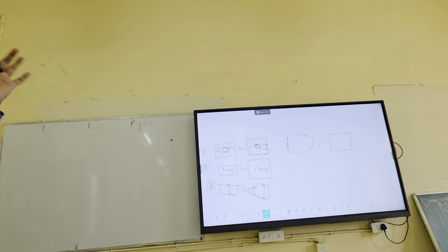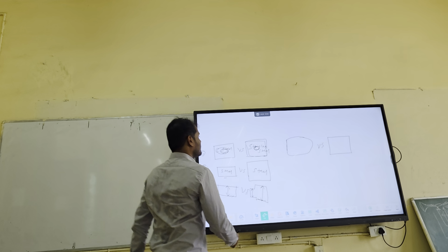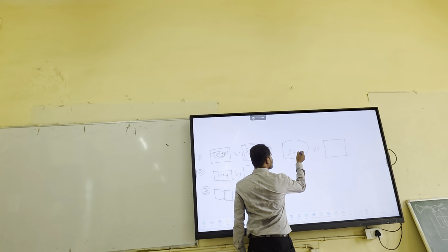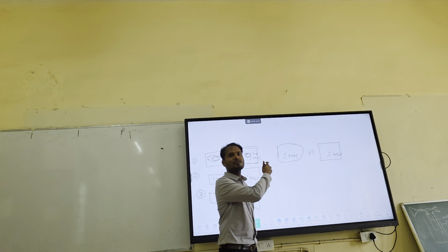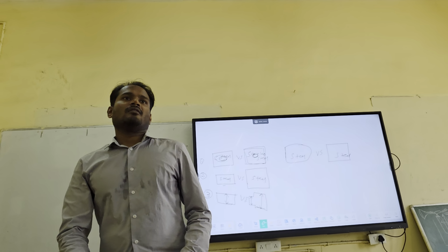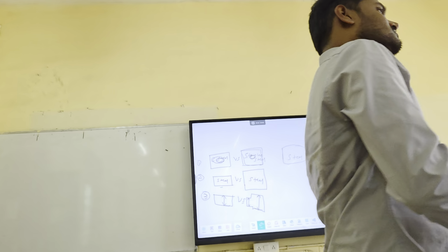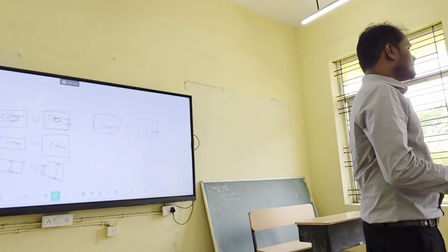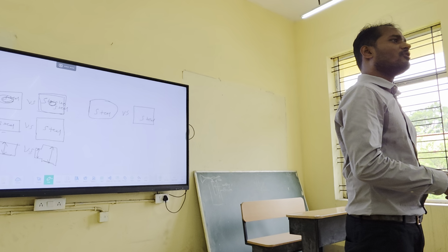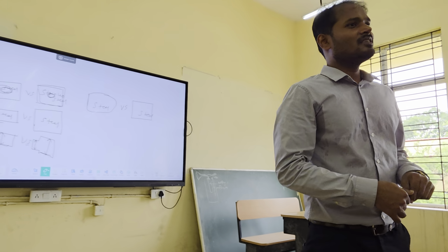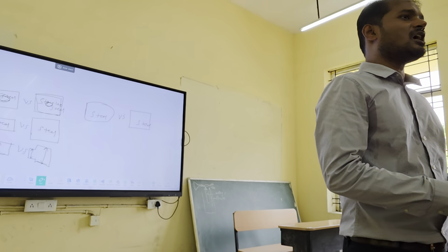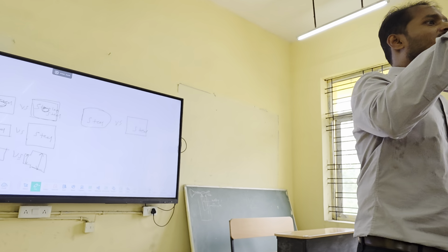And the last one, you can see sharp corners are there, and in this there is no sharp corner. The material is the same, no? Steel maybe. So what do you understand? In this case it is low, in this case it is high because sharp corners are there. You know that sharp corners are always stress concentration sites. You know this from DBA. That's why you always avoid sharp corners in structural applications.